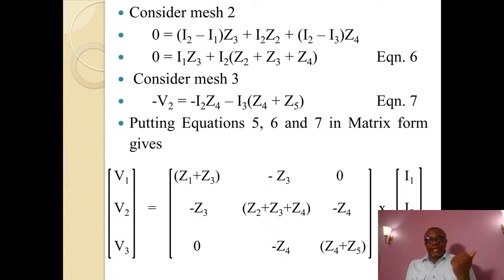V2, like before, we put the minus sign to show that V2 is working against V1. At the end of the day, if it happens to be positive after solving, it means that two of them are supplying together. If it happens to remain negative, it means that one is charging the other. That is the essence of using a battery to charge another battery.